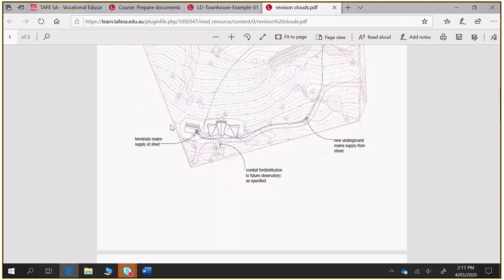Is that something where once you'd done all of your consultation and drawing, and you came down to a final document, you would save it as a new document, a version 2, and just take out those revision clouds for submission? No, typically you don't want to do that because there are drawing sets out there that have the old drawings on them. So you would actually just publish that next version with the revision cloud embedded? Yes.